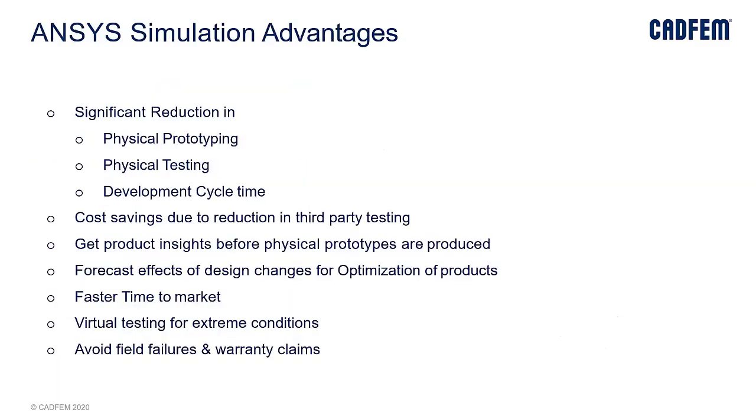Yeah, so this is about the advantages of Ansys, because so far we have discussed the geometry creation, the electromagnetic simulations, and the transformer simulation using the electromagnetic solver, and the outcomes like the losses, the forces, or the computation of faulty scenarios. Apart from this, we have done the multiphysics environment for the thermal analysis and the structural behavior of the transformer. So more or less we have covered the complete comprehensive solution for transformers.